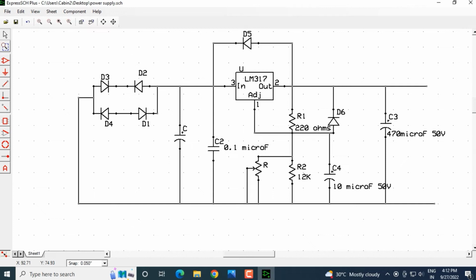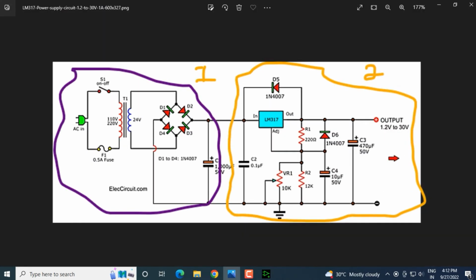So now let's connect the transformer here, and then that'll be a lot easier. So then eventually you would have completed the complete circuit. We would have drawn the entire schematic. And out here you can see this is AC in. It's an SPST switch. That's a fuse, and that's a transformer, a step down transformer.